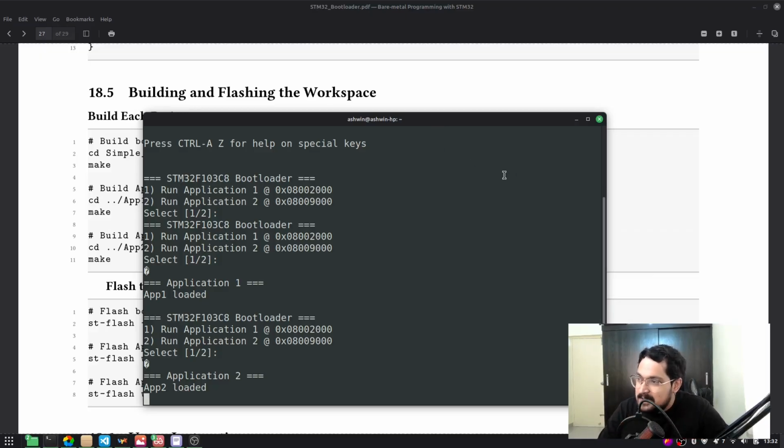Okay, all the best. In the next session, we will do a flash loader where we will be writing into the flash. The bootloader will take bytes from our hex file on the PC, and a script will talk to the UART, and we will write the bytes to the flash and jump. So that will be a proper flash loading bootloader.